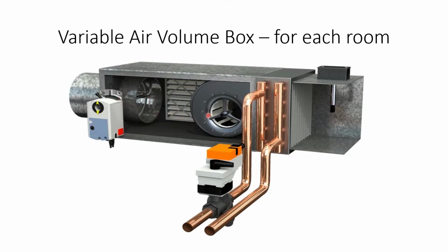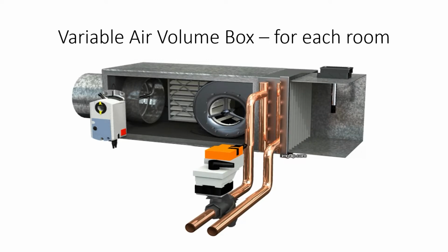And that cool air is brought into the room with the fan, and the heating coil stays shut during the warm months. In order to temperature tune the room, if it's calling for heating, a damper will first open to let in that mixed bulk air, and a variable air volume fan will start. Next, a valve actuator opens to let hot water from the boiler into the heating coil. Mixed air from the bulk air handling system will flow across the coil to heat the room. Let's think about that room as we move to the next slide.